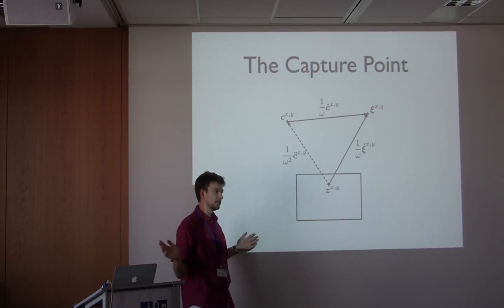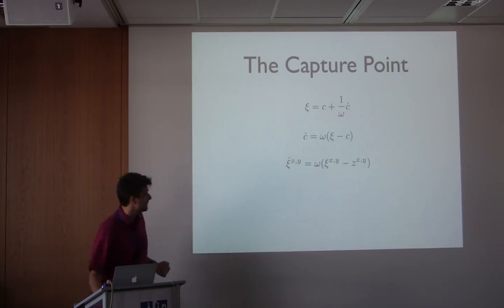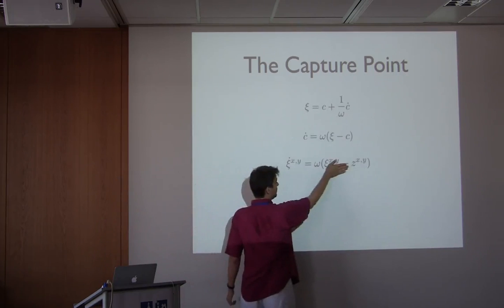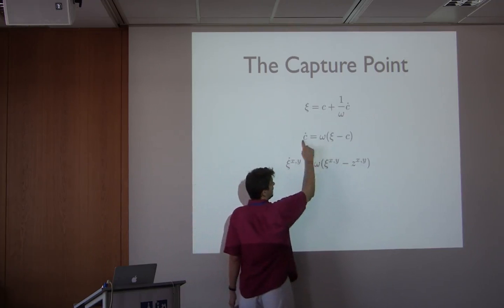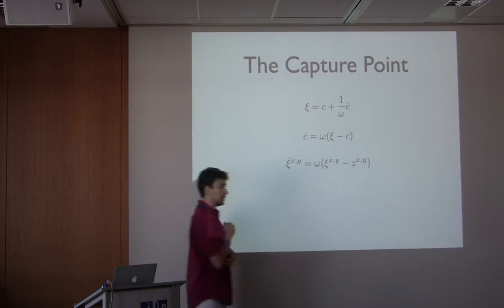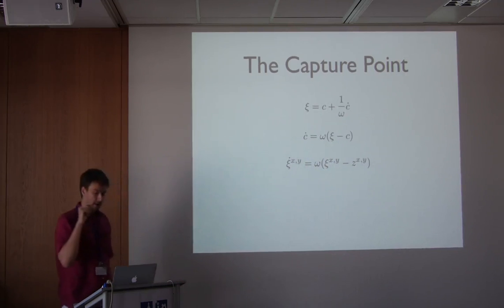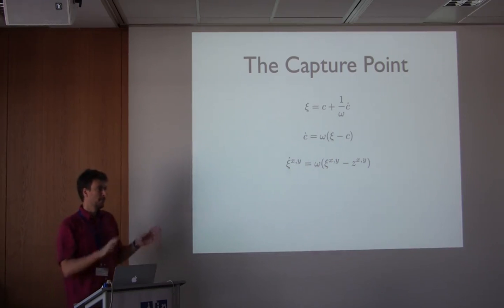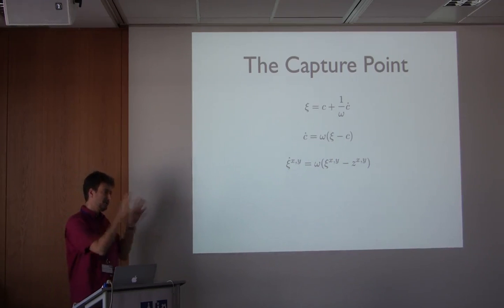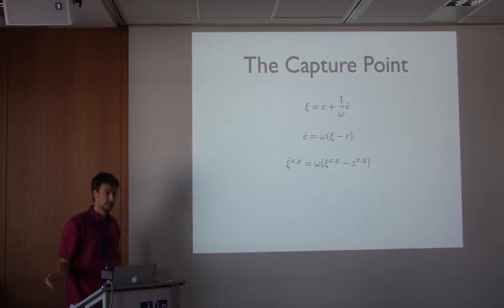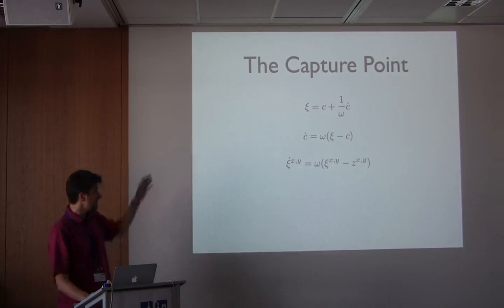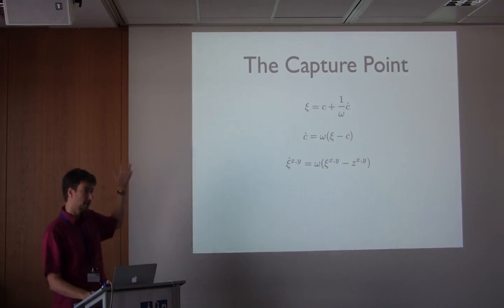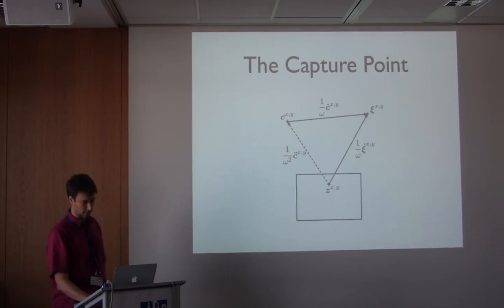You can see it in the equation here. Here you have 0 speed, and then you have c dot, which is converging to 0. So the capture point can tell you that if you put your step there, you're going to stop. So that was quite new. You see very simple equations, but a major observation in understanding the importance of this.